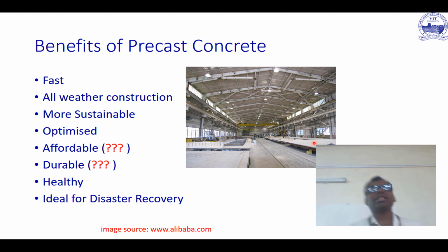It is more sustainable than conventional construction because the amount of material used is lesser. Again, if you take the case of cast-in-situ, wastages will be much higher than what we have in precast yards. Because you are using modular construction, there's a lot of reuse of formwork and other elements associated with concrete. So it is automatically getting optimized.